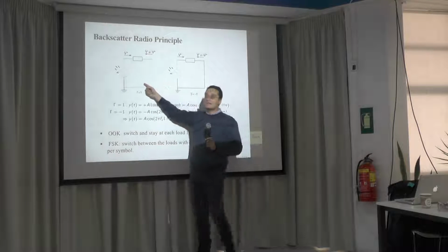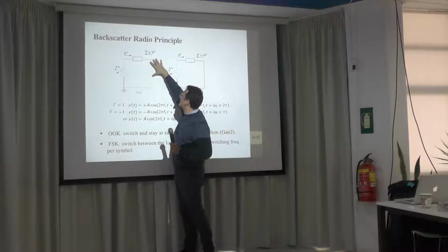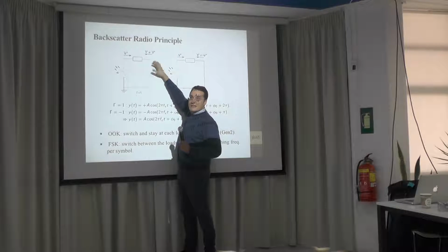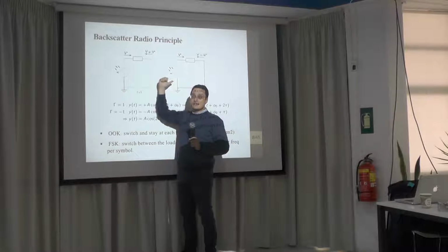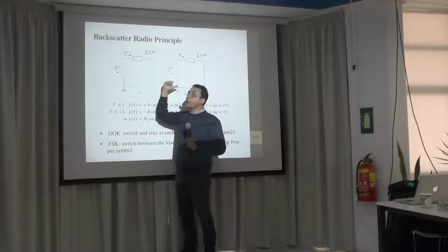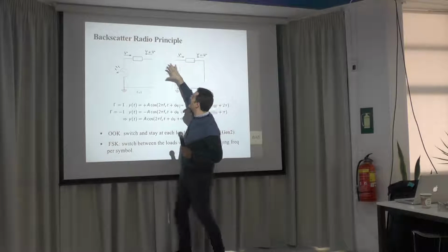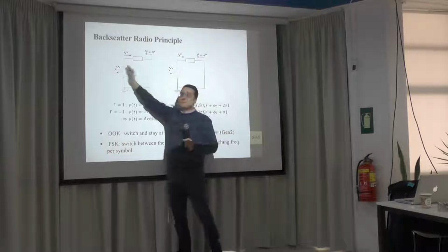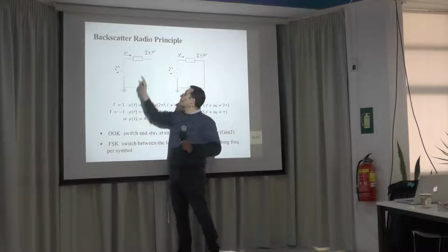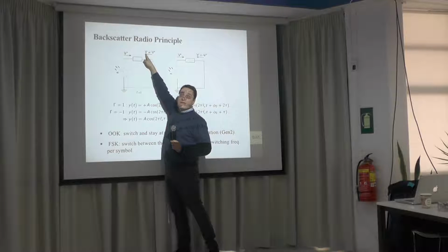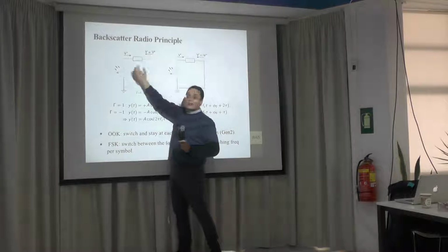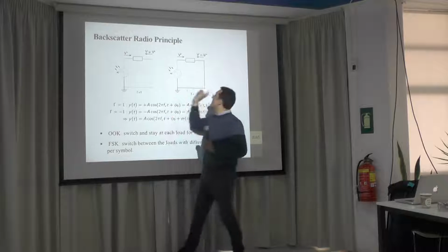What's the voltage difference here, exactly here? I have infinite impedance, right? Because I don't connect anything. So the voltage difference that impinges here should be exactly the same as the voltage difference that gets reflected back. So here, the reflected signal has exactly the same sign as the impinged signal. See the difference?